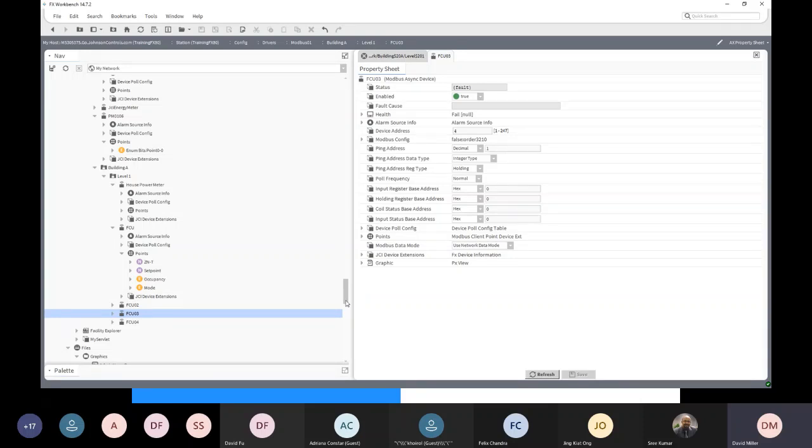Okay? And so if you're a slave device, you just sit there listening. When you see a message with your name on it, you read it and respond to it. If it doesn't have your name or your address associated with it, you just ignore it. So if you're a slave, you just listen and reply. If you're a master, you send out a request and you wait for a reply. Okay, and so that's half duplex. Only ever one device is transmitting at a time, and it's either the master making a request or the slave replying to a request.